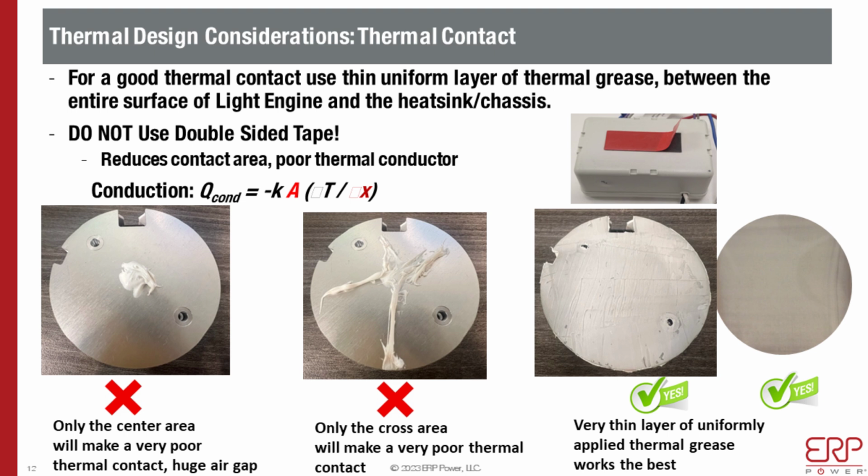What you want to do is apply a thermal grease, or you could use very thin, very conductive gap layers, but thermal grease is good enough, and Arctic Silver is a good brand. We're not advertising that, but try to use a good quality material. The key thing is that you want to apply it as thin as you can and as evenly as you can. These are two very key parameters, and I show pictures there.